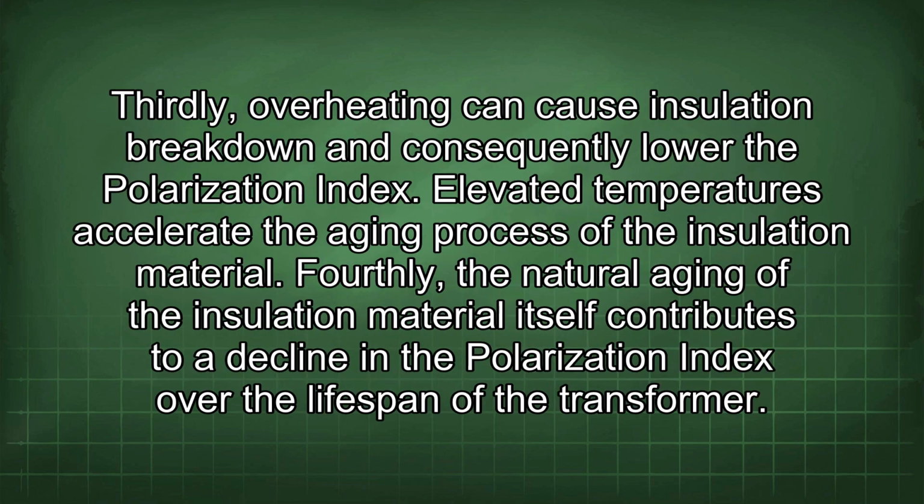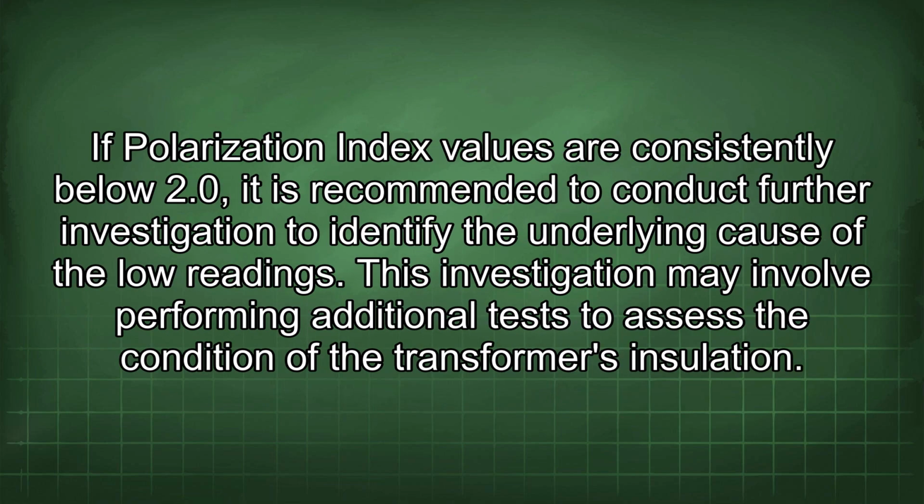Thirdly, overheating can cause insulation breakdown and consequently lower the polarization index. Elevated temperatures accelerate the aging process of the insulation material. Fourthly, the natural aging of the insulation material itself contributes to a decline in the polarization index over the lifespan of the transformer. If polarization index values are consistently below 2.0, it is recommended to conduct further investigation to identify the underlying cause of the low readings.